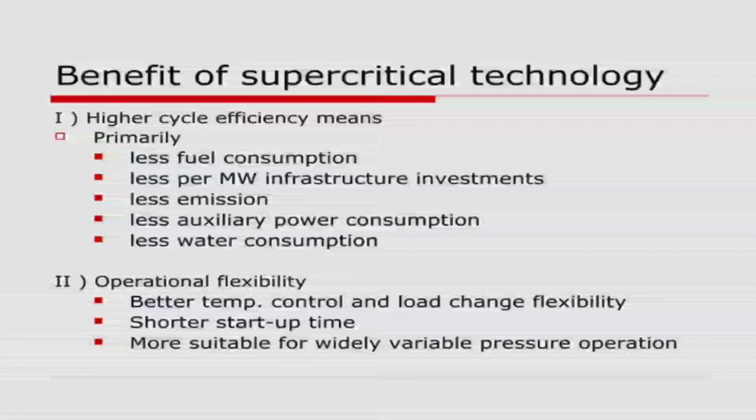Benefits of supercritical technology. It has a higher cycle efficiency, meaning primarily less fuel consumption, less megawatt per infrastructure investment, less emission, less water consumption, and less auxiliary power consumption. The second is operational flexibility. The first one is better temperature control and load change flexibility, and shorter startup time. Third is being more suitable for widely variable pressure operation.